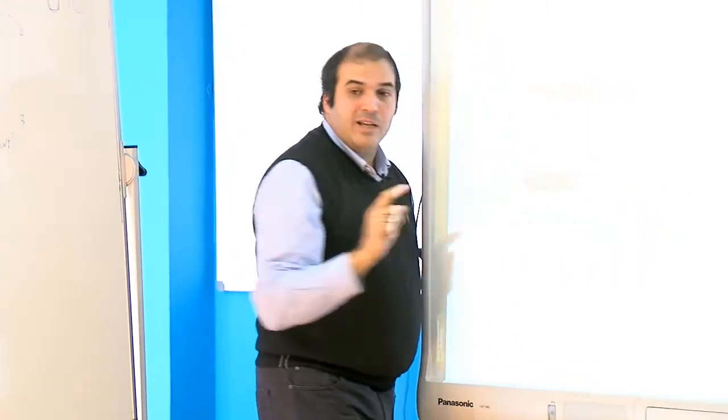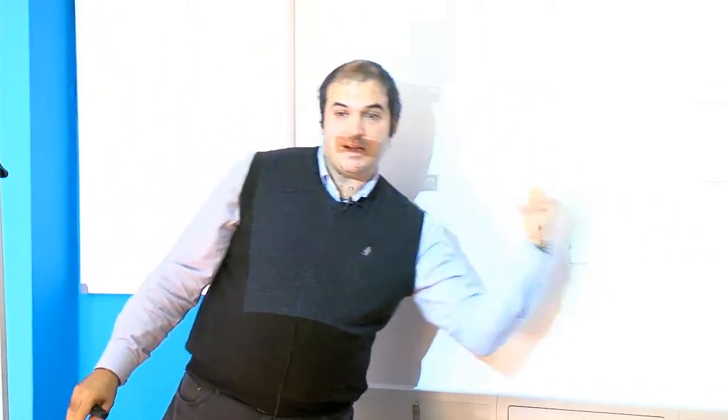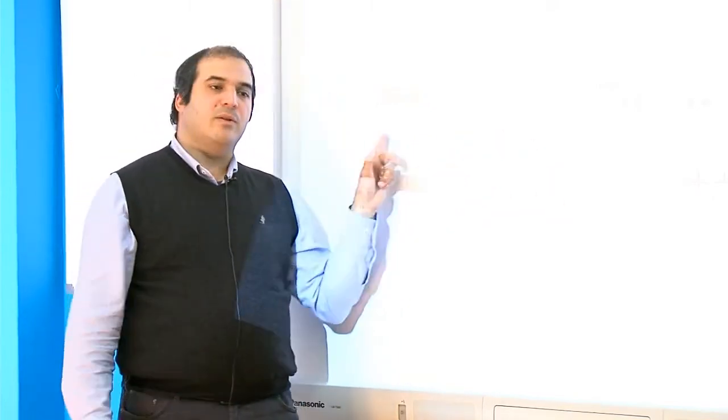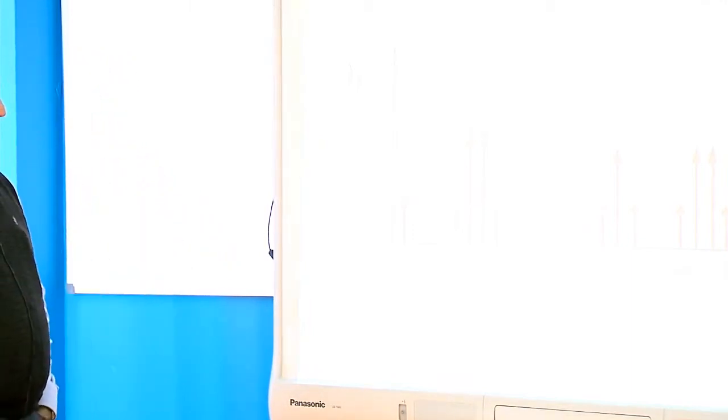And these are isolators, which means that in this direction, they will attenuate 0.5, 1 dB. But if the signal comes back, it will attenuate 20 or 30 dB, which means that even if I have a signal coming here, it will be attenuated 20 or 30 dB, so it will generate lower values of distortion there. So this is very important to use when you want to guarantee that you are getting a very good result or a very good measurement.